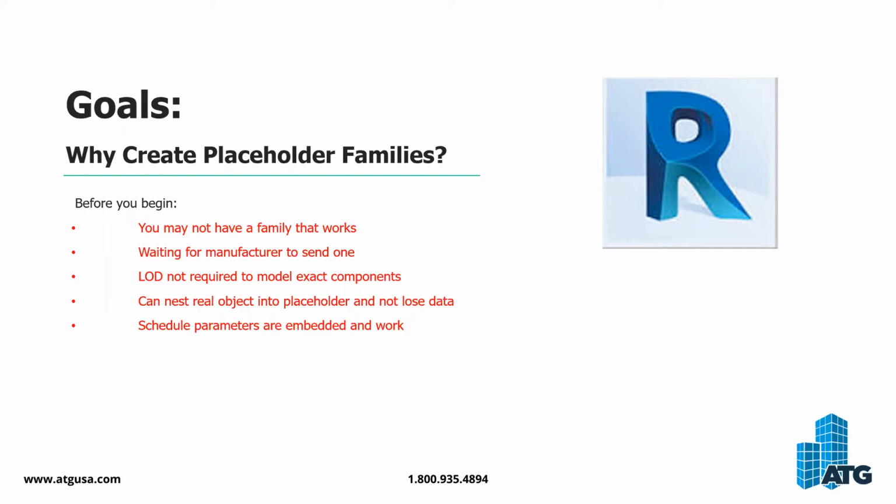If you think about Revit template families, there's a host of those that come with your Revit out of the box software, and a lot of those are very specific things like generic models or doors. Those have typical templates because they need to be associated to objects like walls, ceilings or faces. So a lot of those are pre-built for you as a starting point with some specific rules for those types of objects.